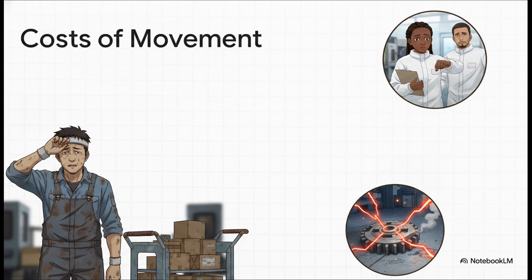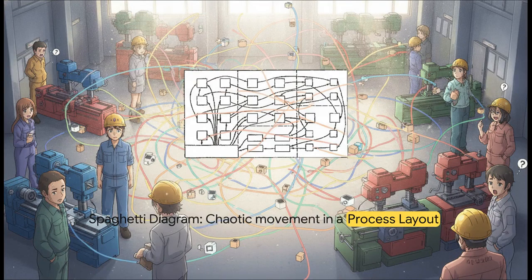But worse than all of that, when a part travels, basically only 3 things can happen. It arrives perfectly, it ends up in the absolute wrong place, or it gets dropped and damaged in transit, requiring expensive rework or scrap. So 2 of those 3 guaranteed outcomes are terrible for your bottom line. And meanwhile, your downstream processes are just sitting there completely starved, waiting for those parts to finally show up. So our first primary control strategy to fix this is to redesign the plant layout using what we call a spaghetti diagram to actively minimize that travel distance.